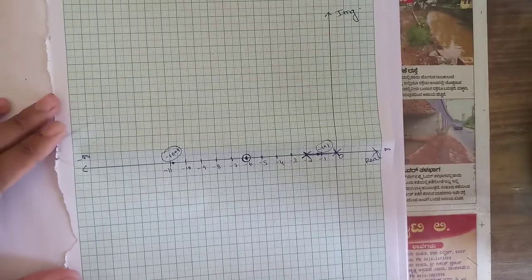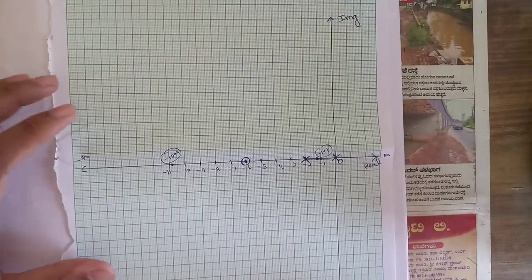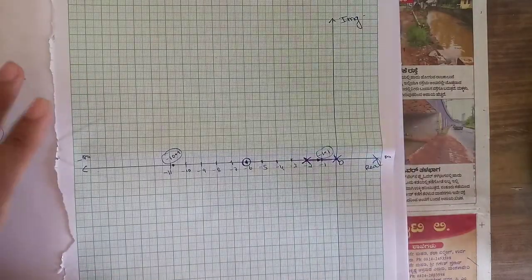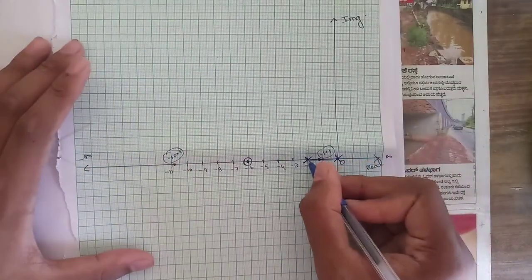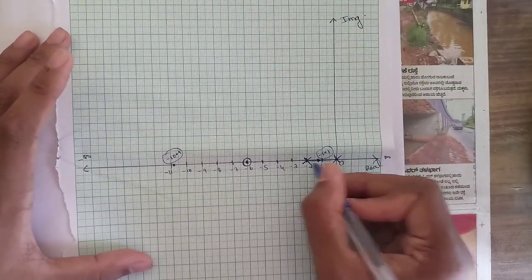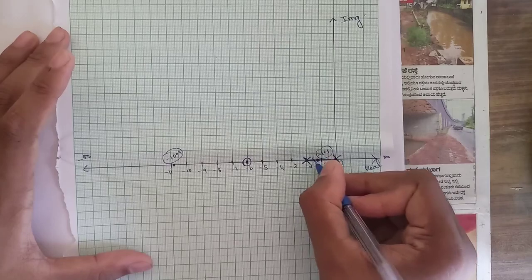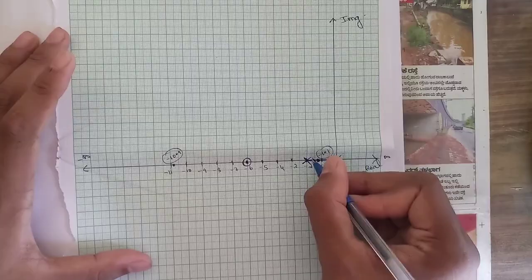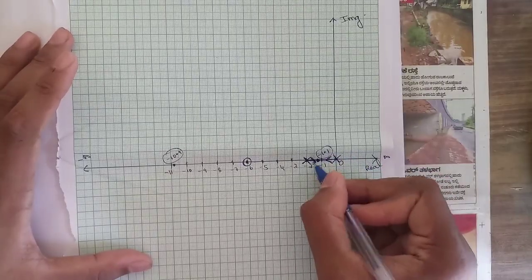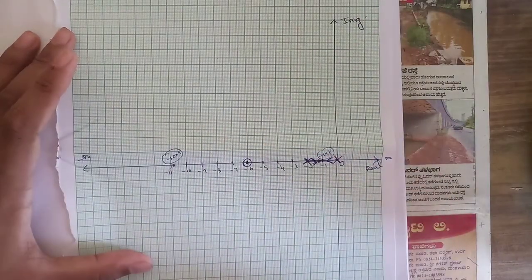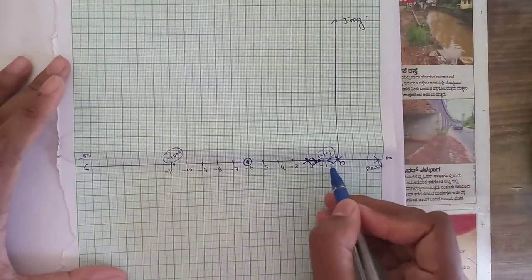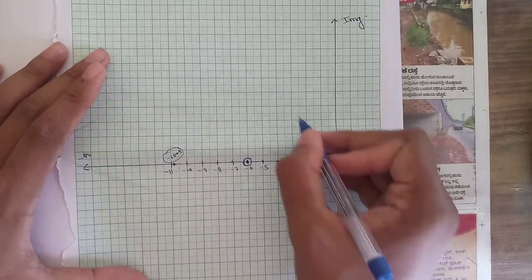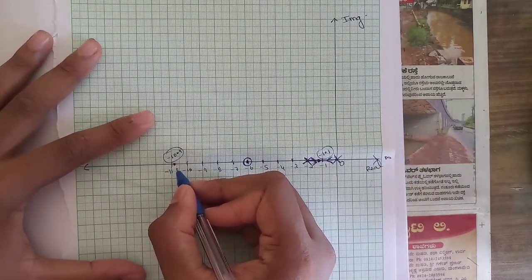Since here we have two breakaway points, we should know that the branches should be approaching both the breakaway points. So how might it be approaching? See, we have two poles here and we have one breakaway point between these two poles. So we can say that these two poles are approaching towards the breakaway point in opposite directions. And from here, it might be going upwards or downwards. It's your wish. You can write it as it is. This direction also it might be going upwards or downwards. And from this point, it would be diverging and it would be meeting this breakaway point.